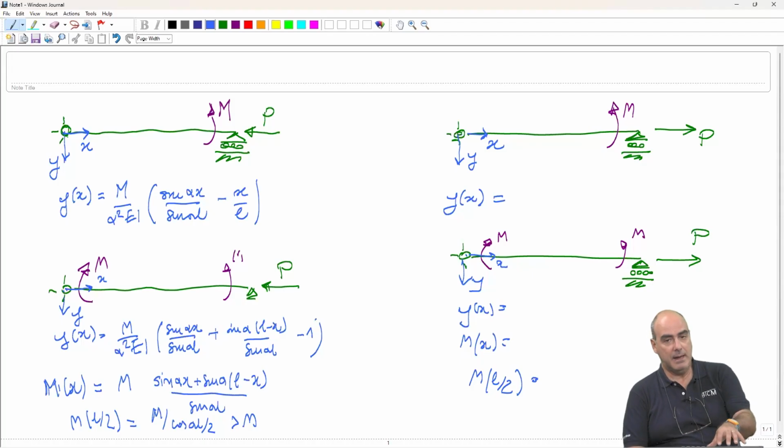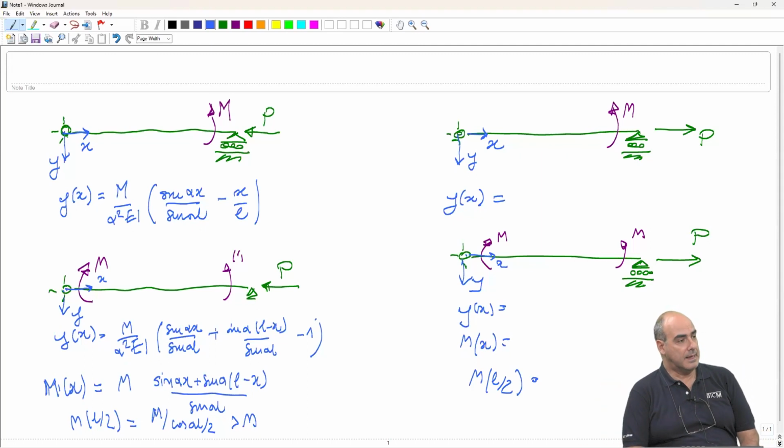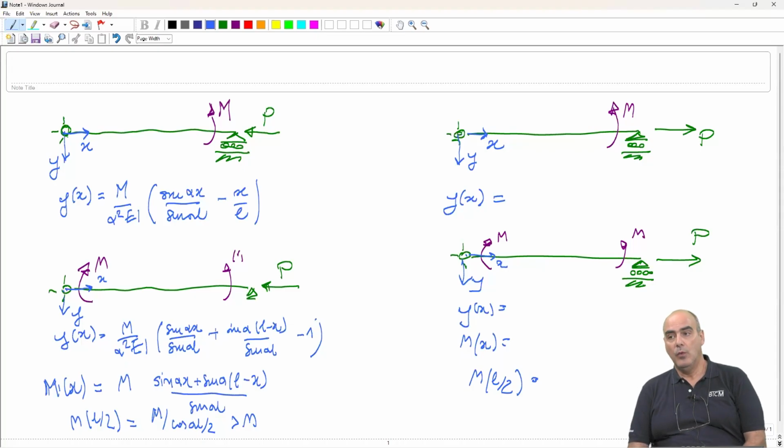And then we ended up studying the problem of the same beam under uniform bending moment, which, because of the effects of the axial forces and the lateral deformation, can acquire some flexural component. The effect of the axial force becomes a moment amplification, which can lead to buckling.